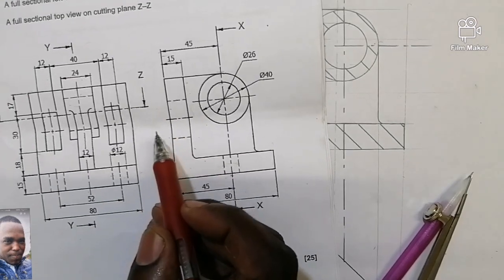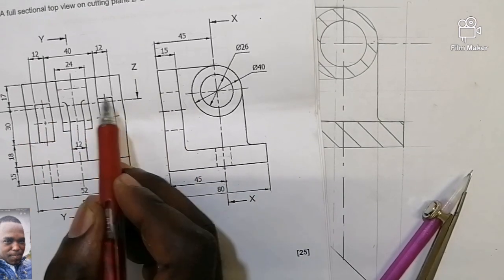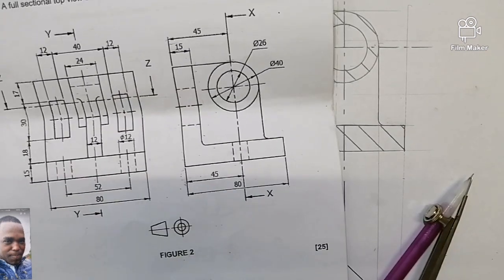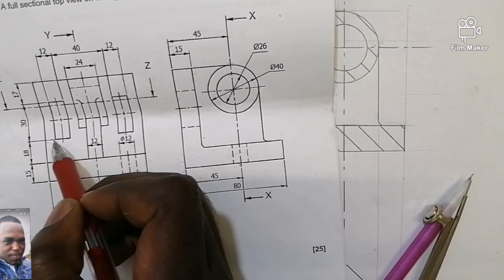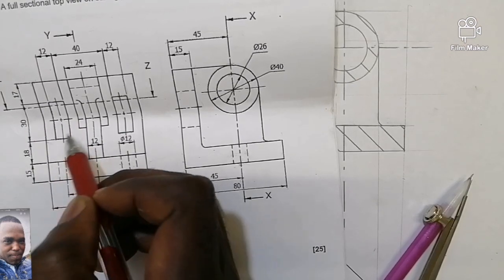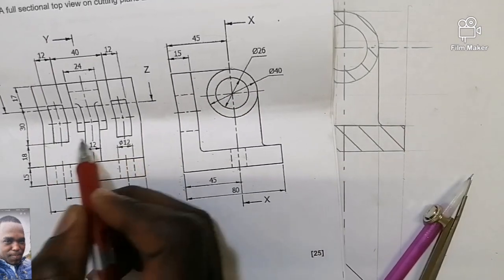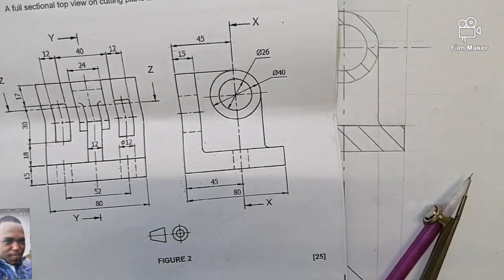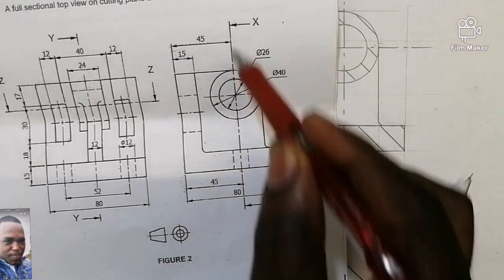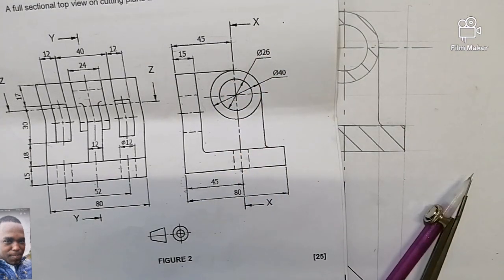Okay guys, you must take a very closer look to say what these are, and when you study them, you must correspond them with dimensions. So they are told from here till here is 30. They are of a height of 30 millimeter, and a length of 30 millimeter. These two on our left correspond with these hidden details, which means there is a gap. They are more like windows, you understand? We can symbolize them like that. If we are tracing the cutting plane of XX, they are not even disturbed, so they have to be drawn.